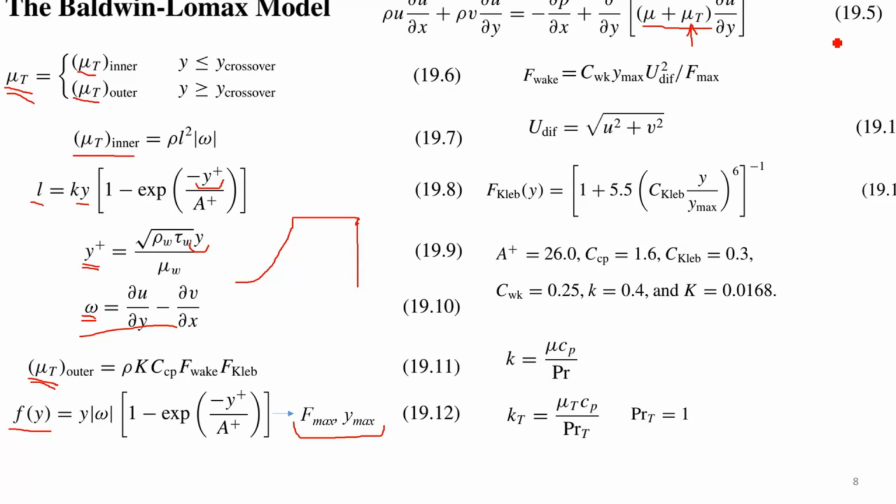These parameters, turbulent viscosity and turbulent heat conductivity coefficient, are not thermodynamic parameters. They are not considered as thermodynamic parameters of the flow. They are received after solution of the flow equations. So they are results of calculations, but they are not independent parameters which we set.